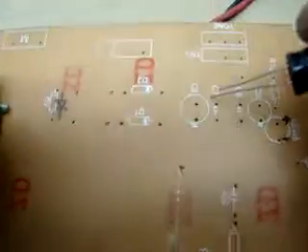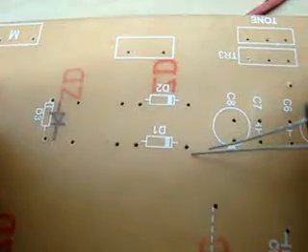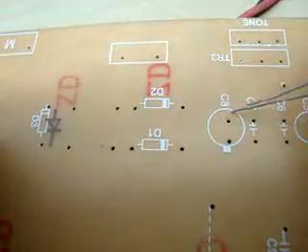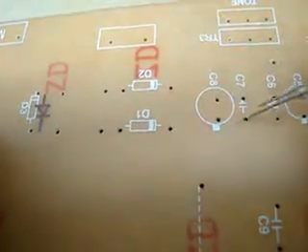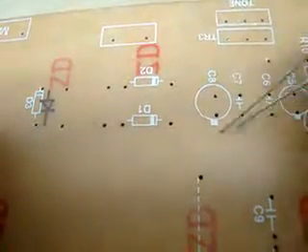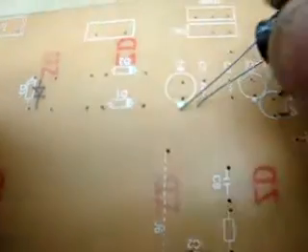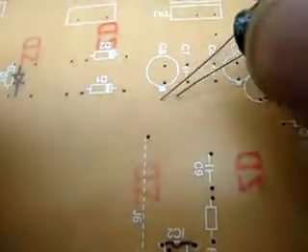So we can insert the capacitor here, C8, and D1, D2 are diodes 1N4007, and in C8 your positive is connected across the upper side and negative is this side. This is the symbol for negative on this capacitor.